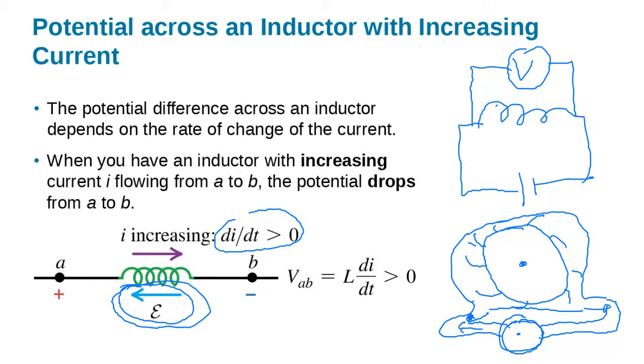And then when we switch the pressure off in our water circuit, so if we stop pumping the water, because this water wheel has got inertia, it will keep spinning for some time and keep trying to push the water around the circuit. In that case, we'll have higher pressure on this side compared to this side.